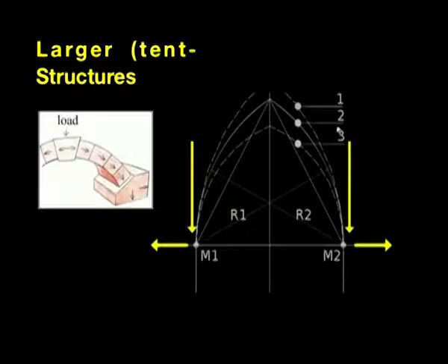If the horizontal loads are reduced, the main advantage that you get is you do not have to provide a big thick column or a pier. You can reduce the thickness of the pier or column. If the thickness of the column and pier is reduced, which means that your overall loading comes down. If your overall loading comes down, you can build taller, you can build higher, and you can go for very large, huge, dramatic structures. This is the reason why all the Gothic churches or Gothic cathedrals have pointed arches